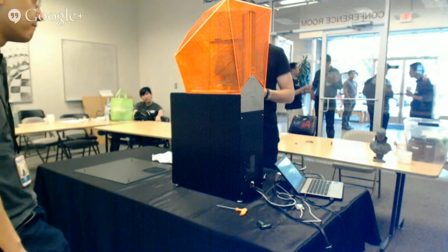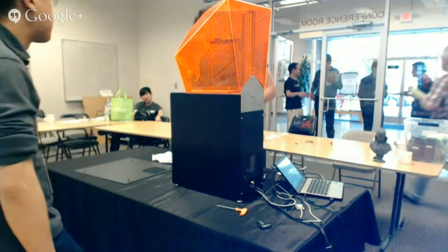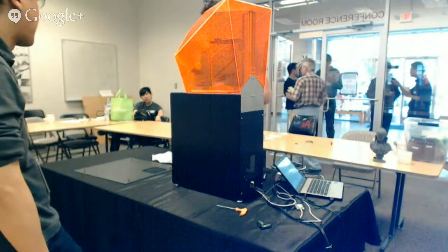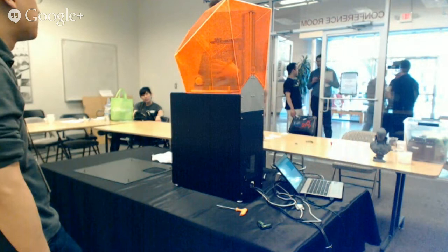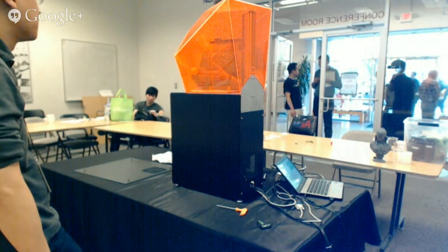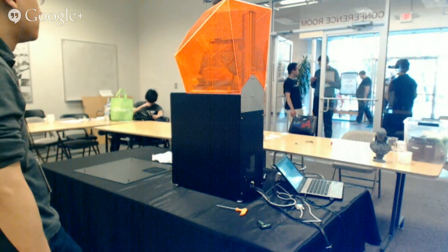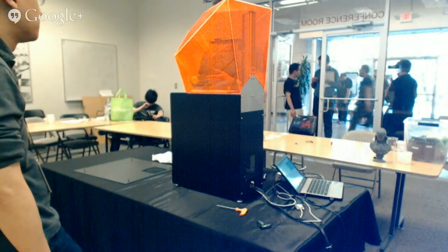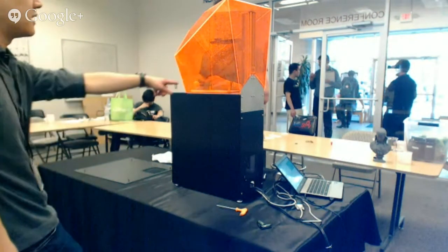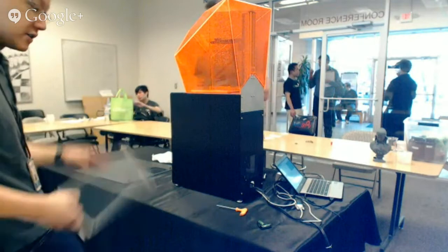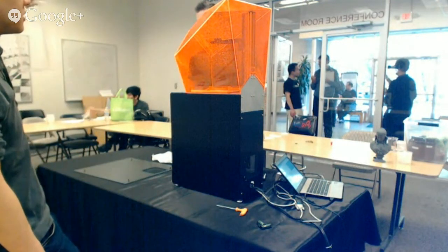So the question I had was, I bought a DLP projector and essentially my first layer's cured and then the next ones didn't. Well, they did and then they didn't stick. What's the negative of overcuring just to get it to work? It depends on the type of vat you have. If you have a vat like this where the surface is a Teflon film, there's no downside. Just pump up the exposure.